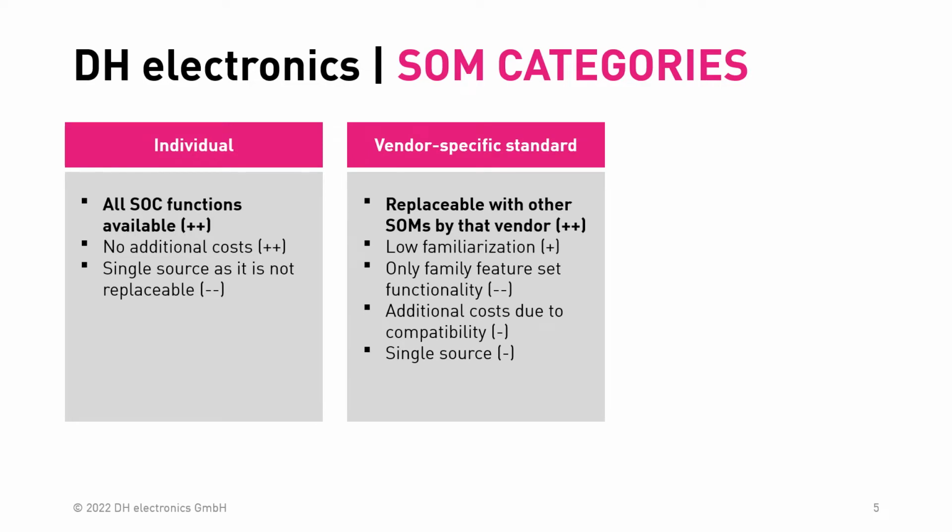Then let's have a look at the vendor-specific standard. Here the big plus is the replaceability with SOMs by that vendor. This means you can switch between different SOMs of that vendor within this specific standard. Then the next point is the low familiarization time. This means if your developers have done a first design based on this standard and they're doing a second one, then this will really speed up your development time, because they know exactly what to do with this standard, and so this can really speed up the development step.